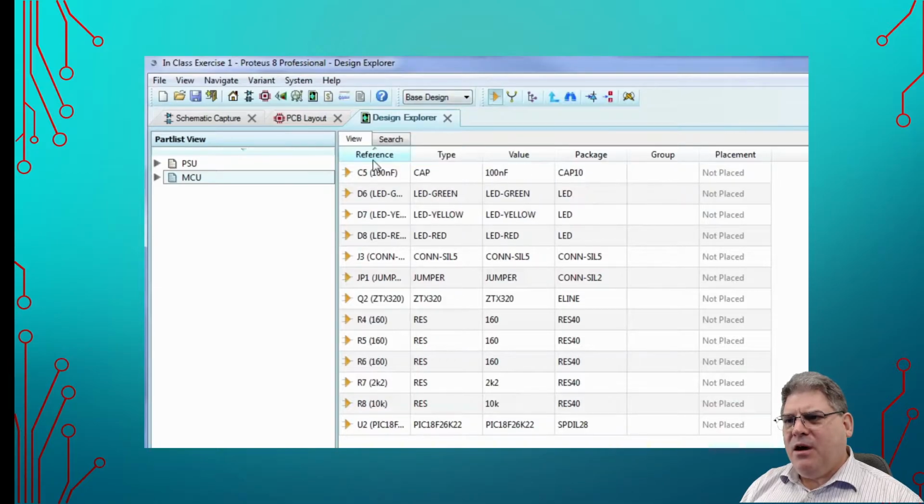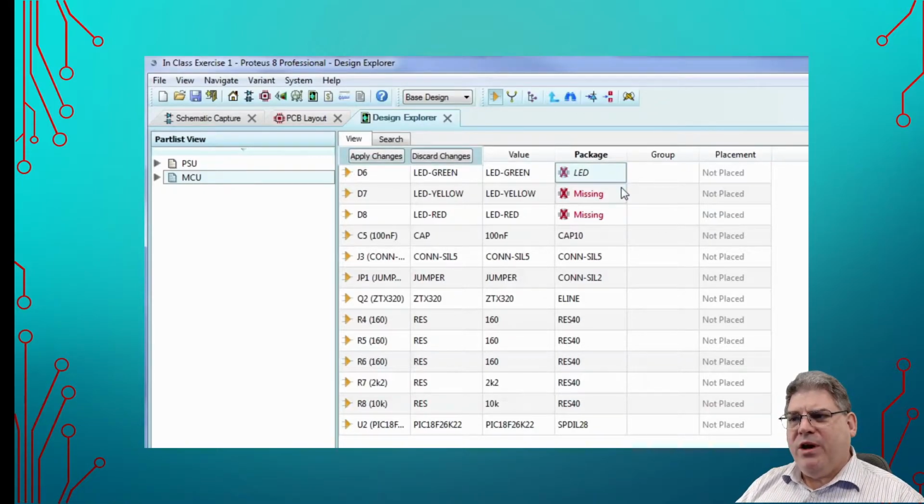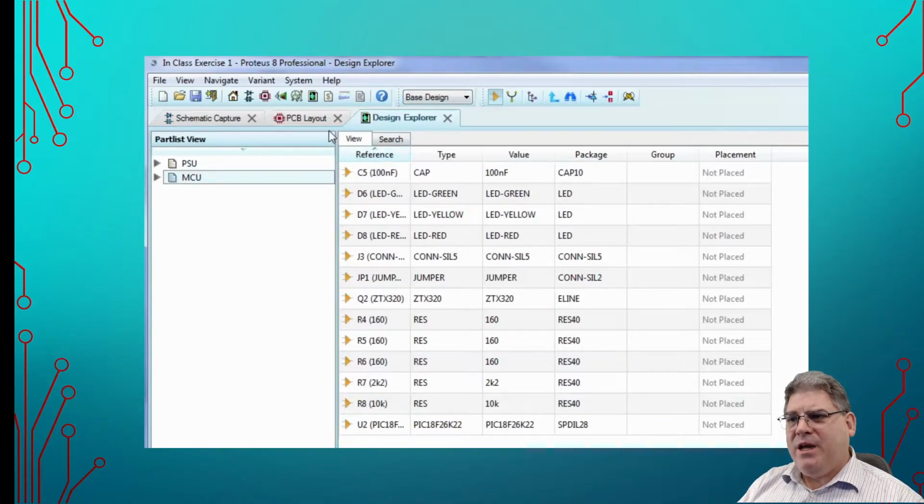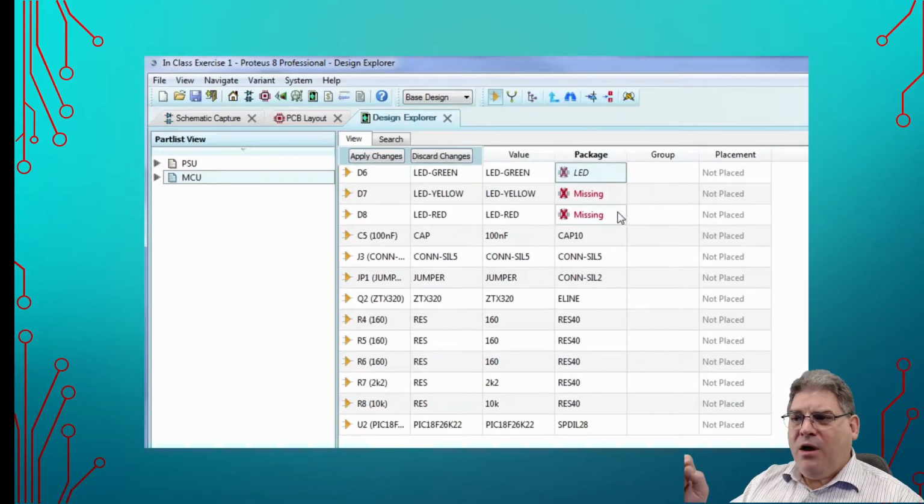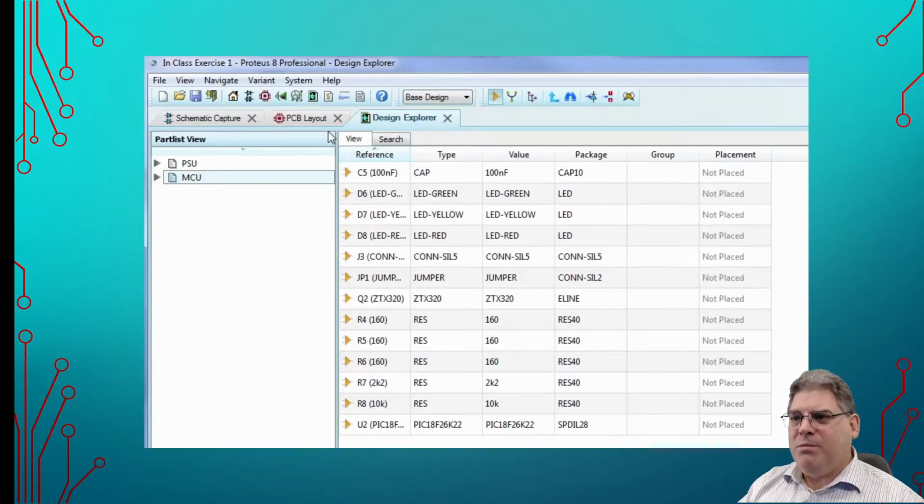And one of the things that I want to show you is basically that we can type in a value. For example, here we know that LED in caps is a part. We used it previously. But you can see here that I'm actually just grabbing the component and dragging it down. Now, word of caution is that you can do this. You can make a huge mistake here where you grab that LED and you pull it down too far. So you end up getting multiple LEDs on things like the capacitor, which would be bad.